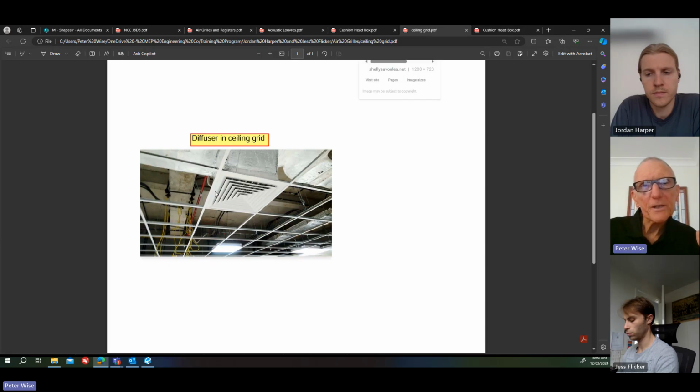And each of those flexible ducts, this is off the top of my head, so don't quote me, but just to give you an idea, each of those flexible ducts would have to be probably 500 millimetres diameter, internal diameter, plus insulation. So it's big flexible ducts, or you can have 6 smaller ones or 8 smaller ones, but then you've got flexible duct going everywhere. And you don't want too much flexible duct because it tends to get squashed.